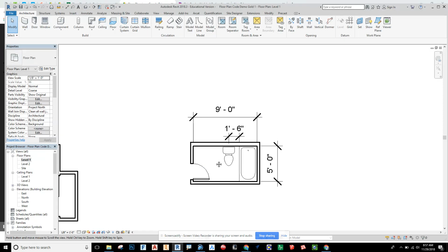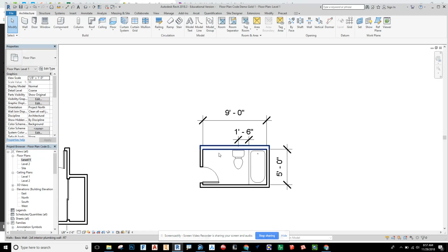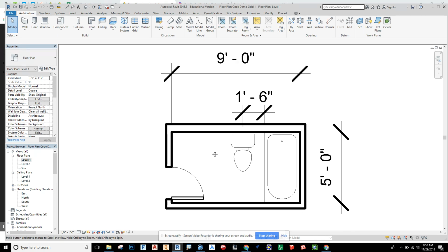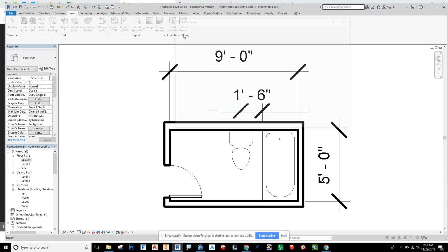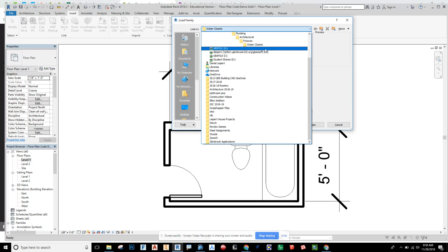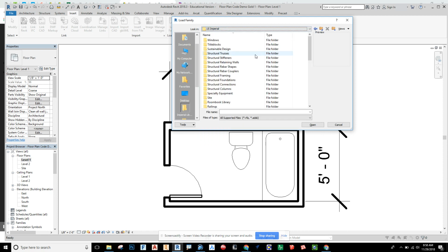Going into our Revit file, here's our plumbing wall. Our sink's going to be right up against that, and we're going to throw that in right here. So we need to search for a base cabinet to start. So I'm going to go to Insert, Load Family. And from here, we're going to back out of this to just US Imperial files.